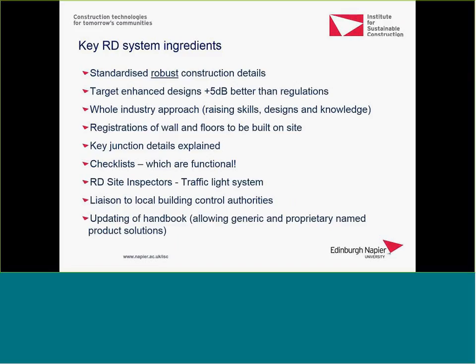So some of the key ingredients we really had to set out from the start. We needed a standardized, robust construction detail approach. We needed to target an enhanced performance better than regulations by about at least 5 decibels. We needed the whole industry approach, raising skills, design, and knowledge. Anything that was going to be built using a robust detail in the future would require to be registered so we could track it.